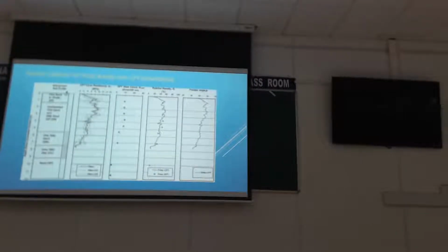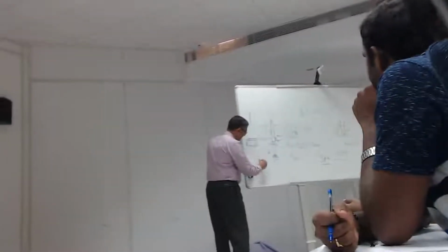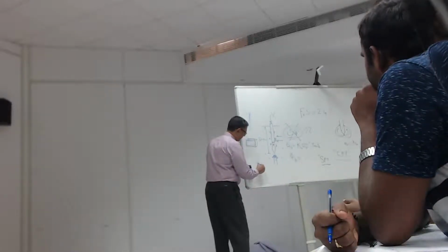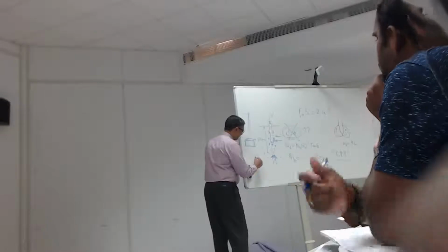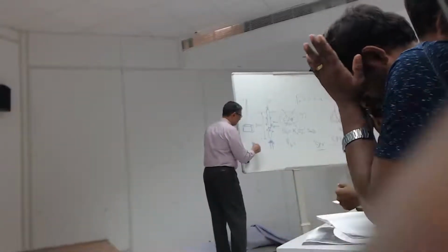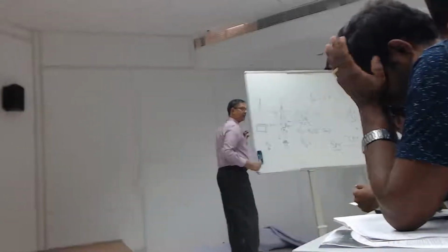And it's quite useful for pile design, because if my cone is like that, and I have a sleeve on this, which is measuring the friction along here, and obviously you need a contraption to carry the load to measure from there.